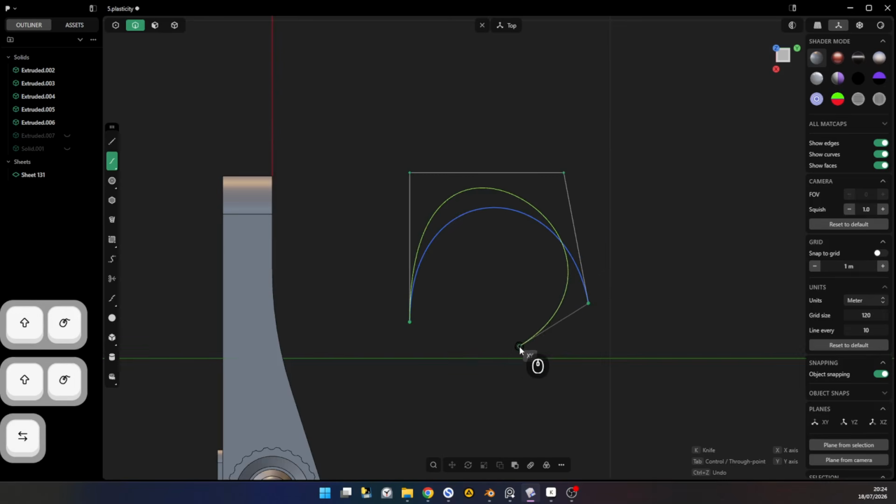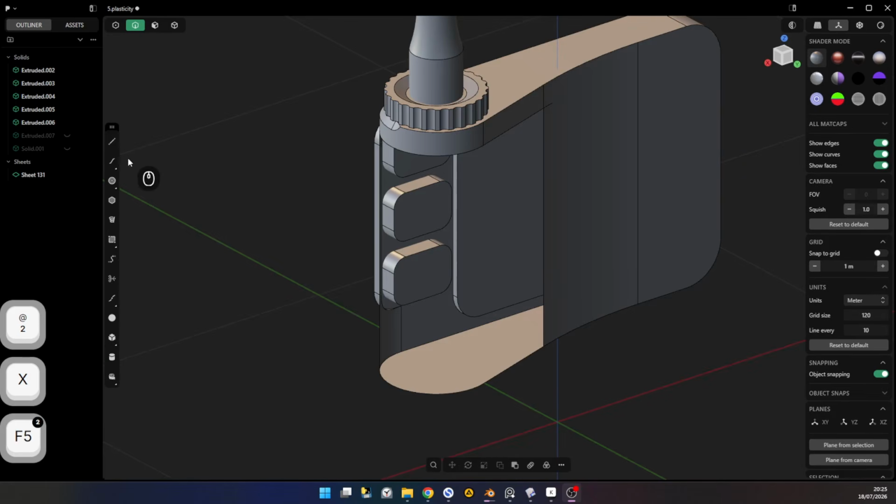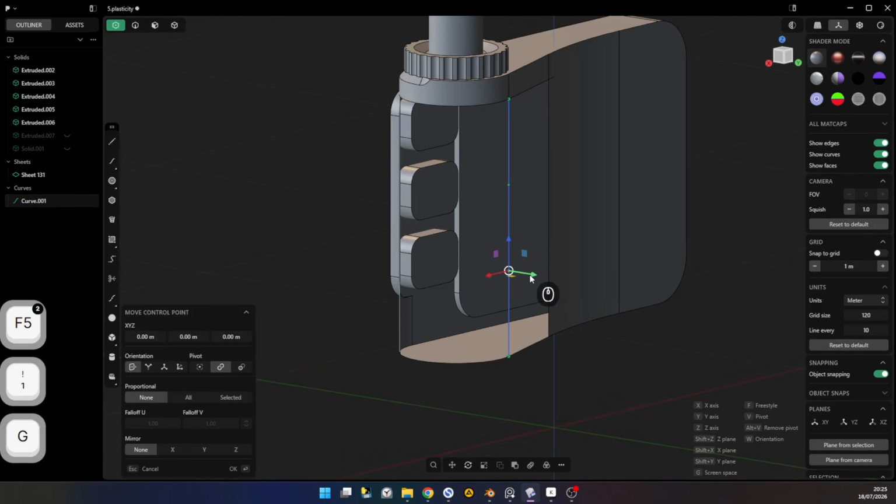So now they are instead control points that we place, and the curve doesn't have to go through them. So I'm gonna select the spline curve, go here, click once, click twice, and end it. Okay, now if I press 1 for control points, I can adjust it.